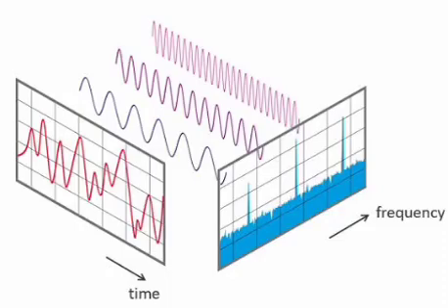Circular convolution can be found using linear convolution. The method is to divide the result of linear convolution into two parts such that the first part has N samples, then add the N corresponding parts in order and write it as circular convolution. Here N is the number of samples in each signal.